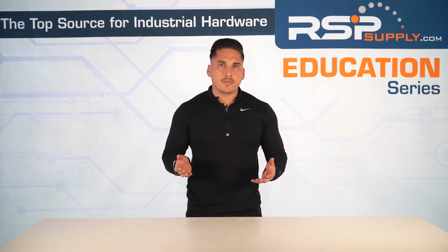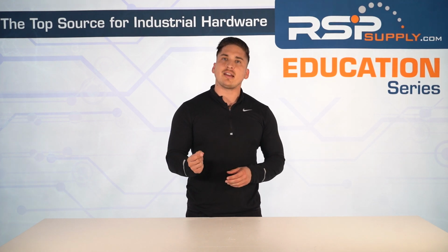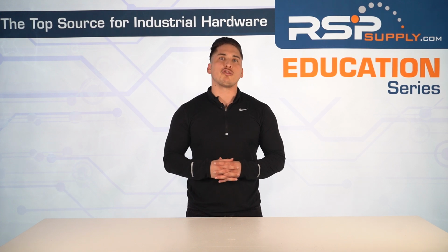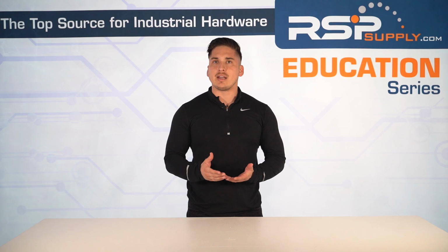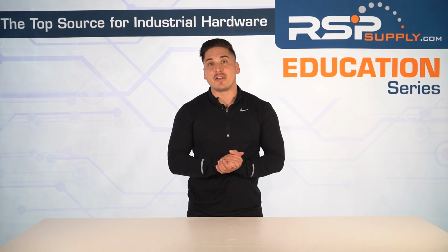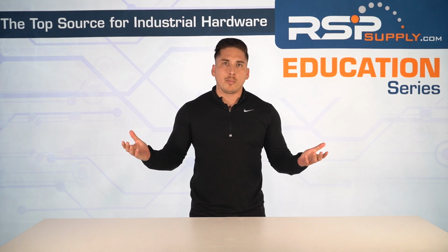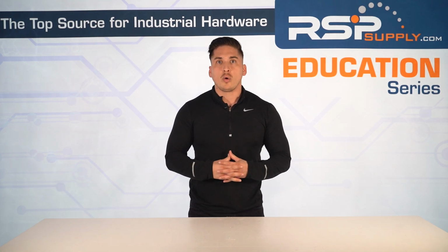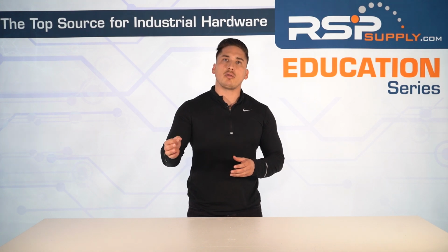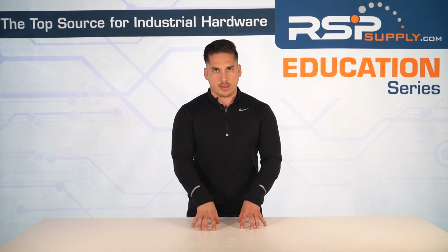So, deterministic versus non-deterministic communication. In industrial automation, machines, sensors, and controllers need to communicate quickly and reliably to keep operations running smoothly. So, how fast and predictable data is transmitted can mean the difference between an efficient system and costly downtime. For example, what if a robot arm misplaces a part, like we said, just 1/10 of a second? Or an emergency stop signal takes a second too long to trigger. In industrial automation, timing isn't just important, it's everything.